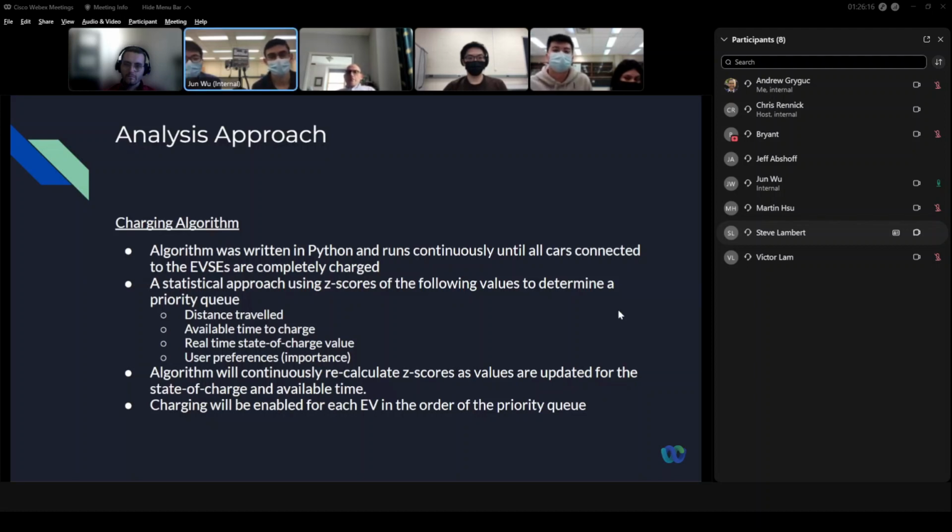Okay, and your system accounts for that and allocates more current to the other EV if the first EV doesn't need 20 amps? Yeah, it does. And how does it actually control the amperage, the constraint that the EVSE sends to the vehicle? It doesn't. The protocol requires that the vehicle does not consume more current than what is available. And the current available at a given EVSE depends on the priority queue that we described earlier.